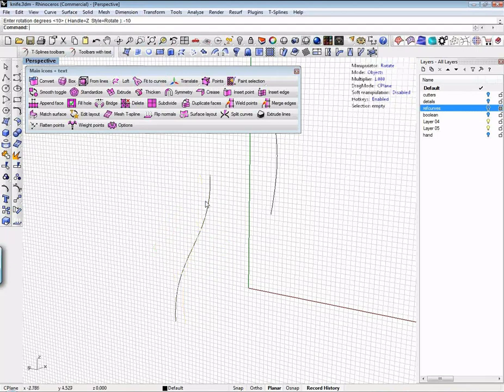Okay? The next manipulator, if I click up here, is the scale. Same thing, I can scale in one direction. I can constrain my scale to this plane. I can constrain my scale to these planes, or if I grab in the middle, the whole object goes up and down. Okay, and again, if I want to do a global scale on this, I double click it.